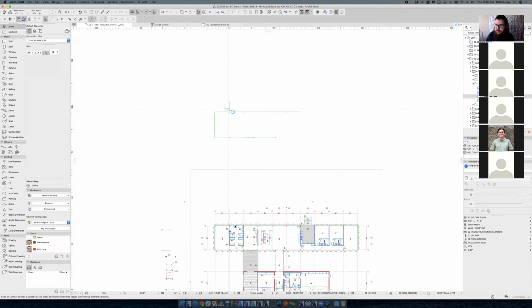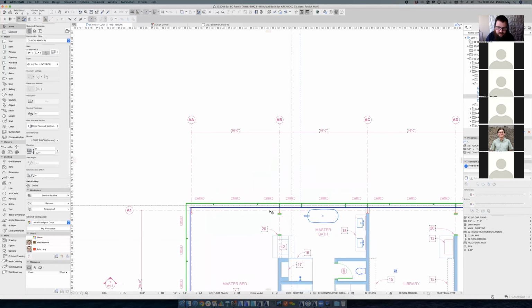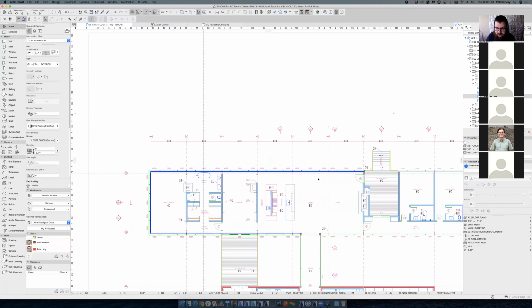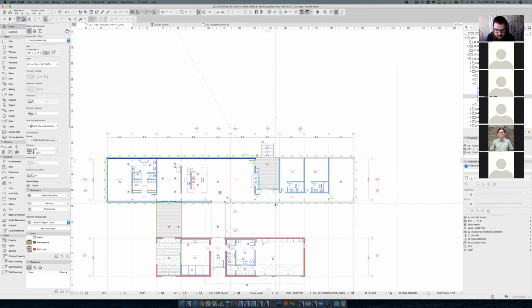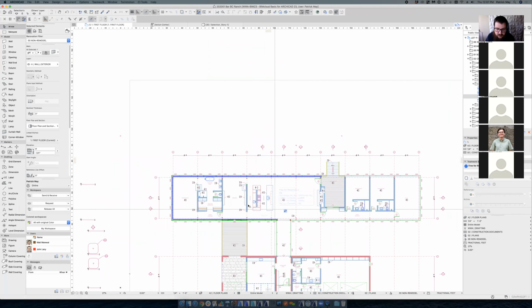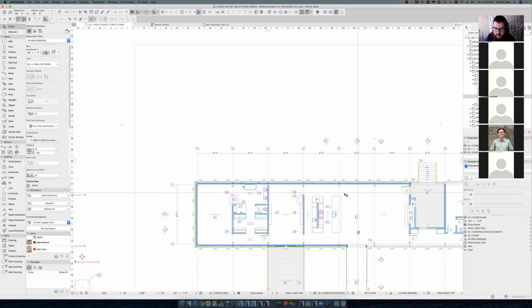I've actually copied over Matt's curtain wall here, but he's used it basically instead of having a wall, and I don't even know how many windows this would be, 100 plus windows and several exterior doors. There's, I think, probably 5 or 6 curtain walls in this project that represents all of those fenestrations combined. So the curtain wall tool can be a very user-friendly way to model something like this condition.